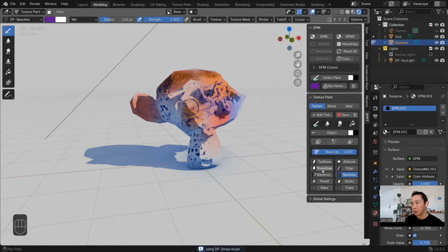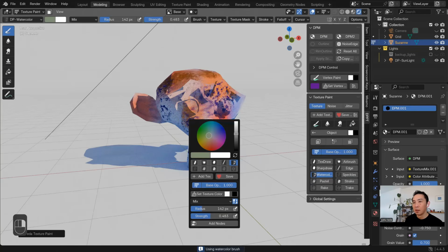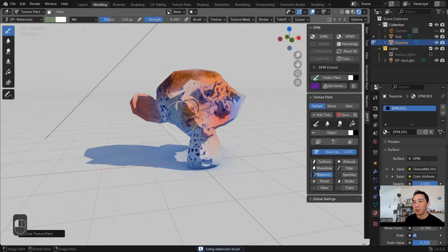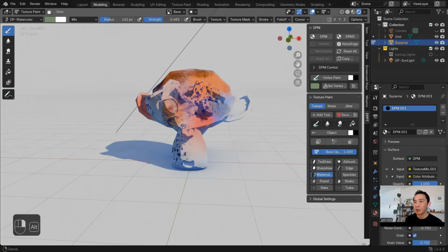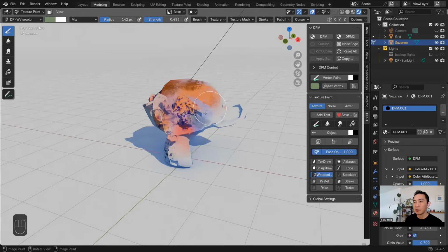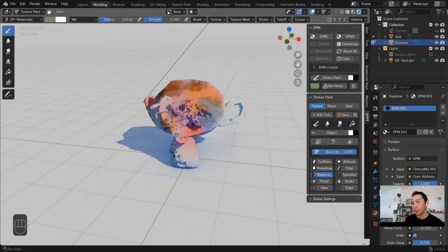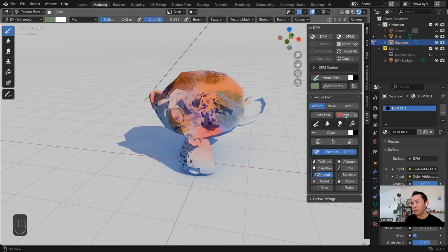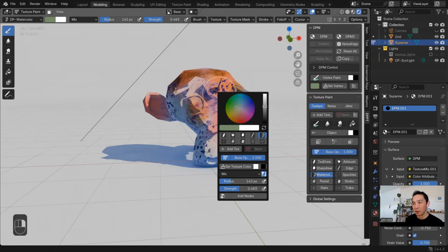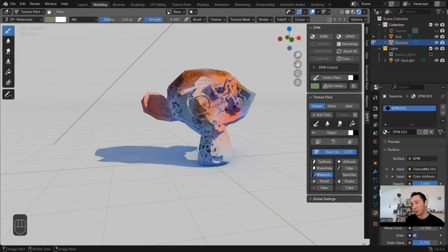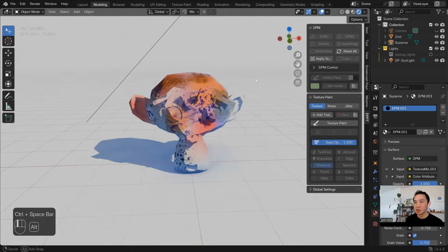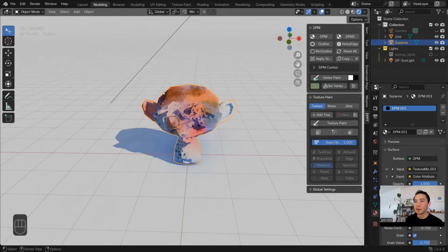So we have these options to paint texture. And then once you like it, or if you want to save the texture, you should do that from here. Save the texture button. You have that in the right mouse button window, and save the texture, right? So this is how you paint a texture map.